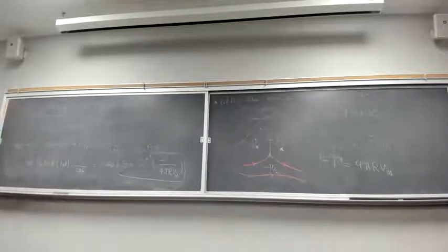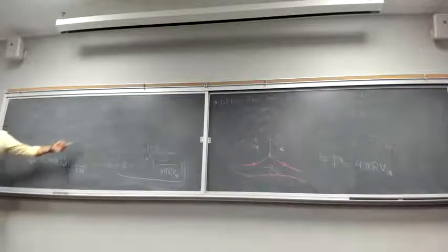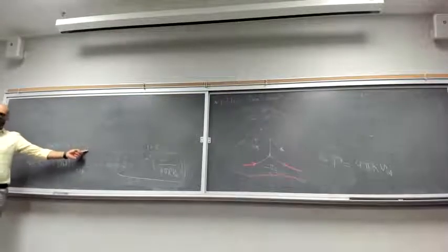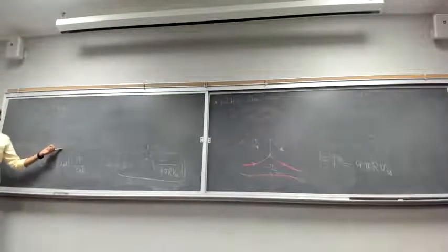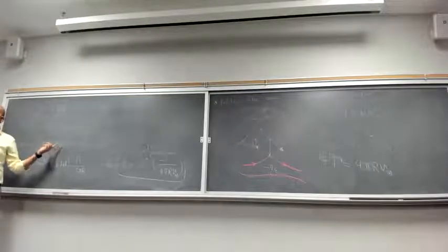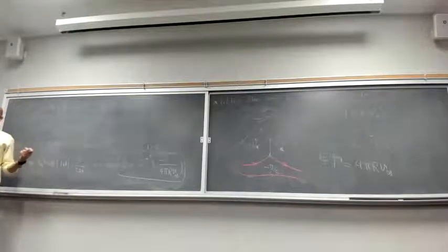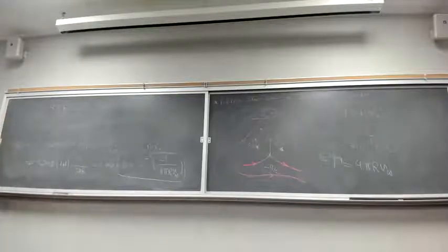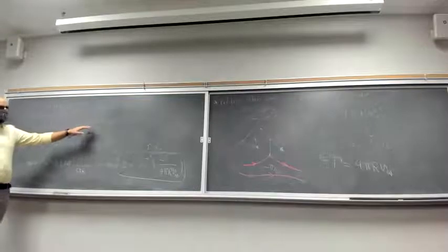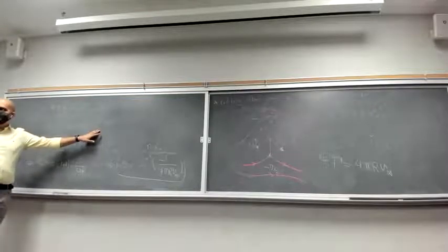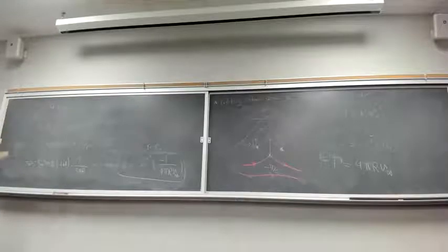So when r cannot be equal to R, then we can safely conclude that your theta is positive or negative pi over 2. And since we want V theta to be 0, this time, instead of plugging in r equals R, we are going to plug in theta equal to pi over 2, right? What is the sine of pi over 2? 1. What is the sine of negative pi over 2? -1, right? So this essentially means that we are going to get two solutions, again two stagnation points. One of them is going to have positive pi over 2, the other one is going to have negative pi over 2 for theta, okay?